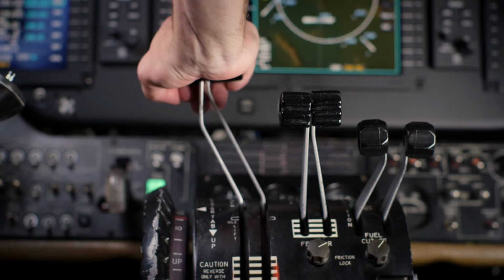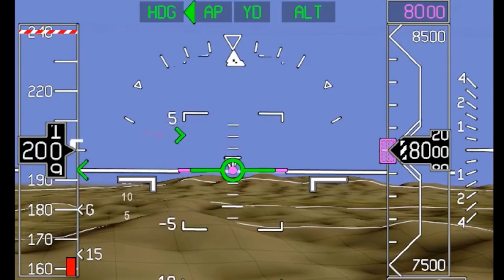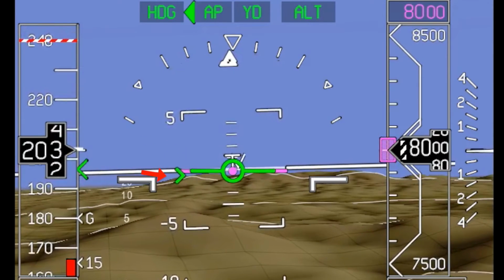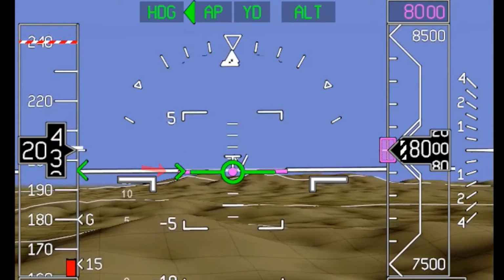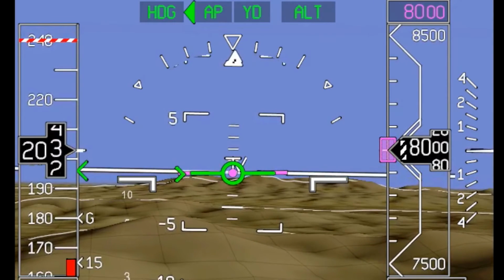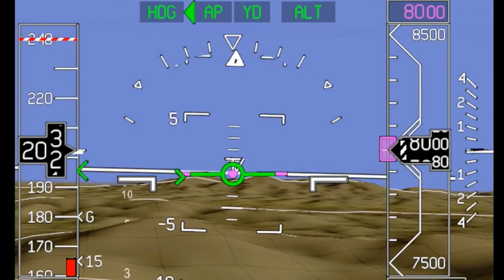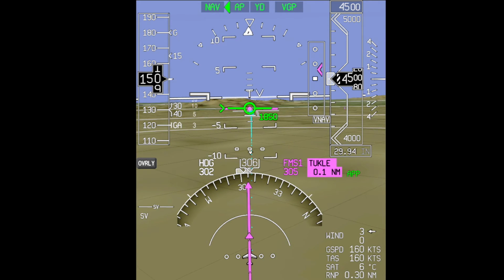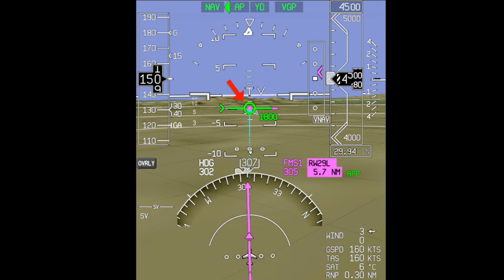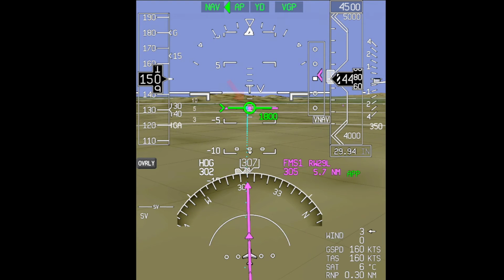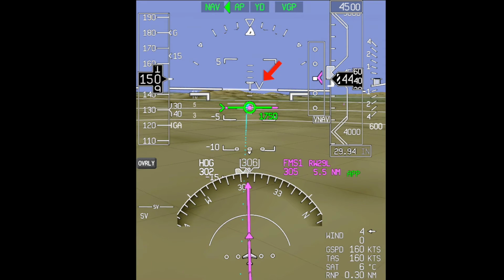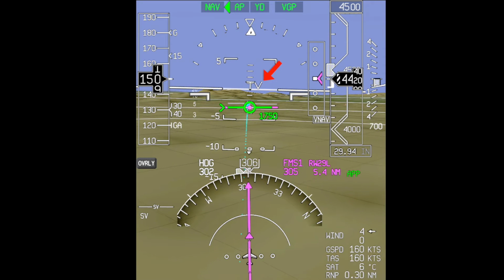The Acceleration Chevron provides a visual indication of whether the aircraft is accelerating or decelerating. It helps the pilot quickly find the power setting to achieve a constant speed climb, cruise, or descent. SmartView's track center display keeps the flight path symbol in the center of the display. This, in turn, keeps the terrain image centered along the aircraft's track and allows the heading symbol to move left or right as wind conditions change.